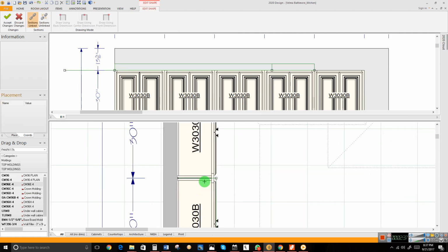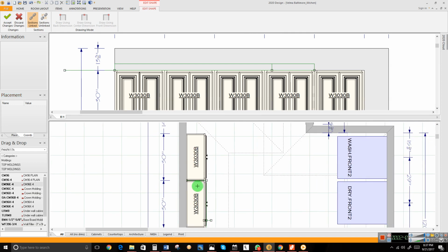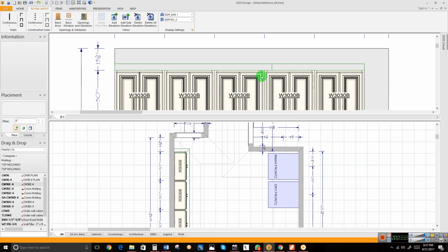Now once you click on edit shape, we're going to be working with lines. This line right here, you can click, wait a few seconds, and pull backwards. All right, that will work. But the best practice is always to right click on the line, and then you see move and intersect. You can move and intersect because that helps to cover up any angle. If it were to be an angle, always remember to use right click, move and intersect. It's going to snap to the endpoint, left click to drop, and then come back up here and you see accept. So you just modified your crown molding.